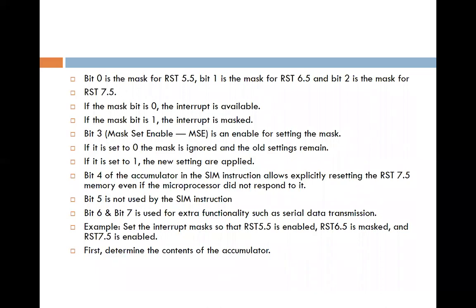Bit 3 is mask set enable. The MSE bit is the enable for setting the mask. If it is 0, then the mask is ignored and the old setting remains as it is. If it is set to 1, the new setting is applied.